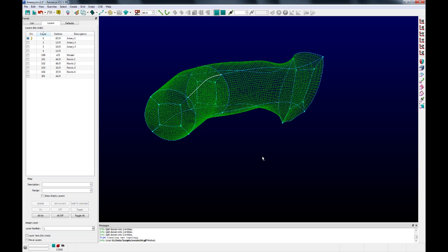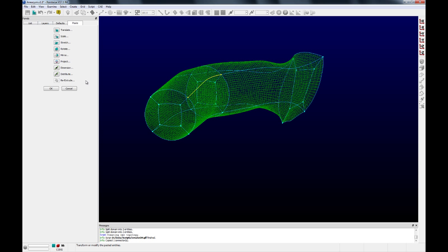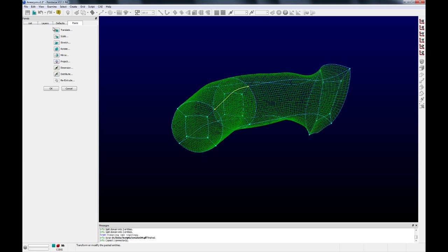It's also by default dimensionally balanced, since we're going to eventually want to balance this connector with whatever we place in between these points there. So we're going to copy with Control C, paste with Control V, and then we're going to be prompted with a number of options for transformations to apply to this pasted connector. So we're going to apply a translation. So we click this. It's going to then prompt us for an offset vector.